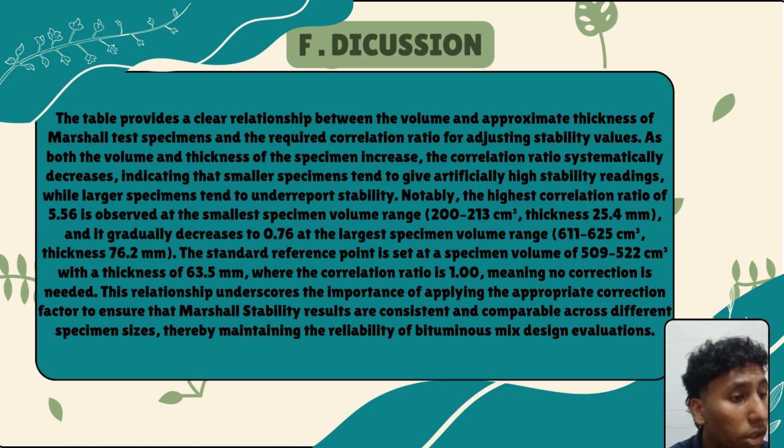Notably, the highest correlation ratio of 5.56 is observed at the smaller specimen volume range, which is 200 to 213 cm cube. Thickness is 25.4 millimeters, and it gradually decreases to 0.76 at the largest specimen volume range, which is 611 to 625, and thickness 76.2 millimeters.